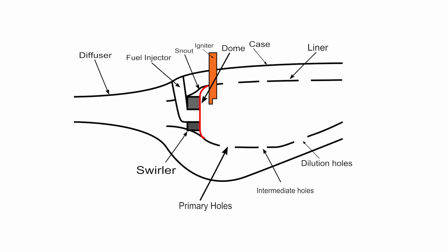The other type of liner cooling, transpiration cooling, is a more modern approach that uses a porous material for the liner. The porous liner allows a small amount of cooling air to pass through it, providing cooling benefits similar to film cooling. The two primary differences are in the resulting temperature profile of the liner and the amount of cooling air required. Transpiration cooling results in a much more even temperature profile, as the cooling air is uniformly introduced through pores. Film cooling air is generally introduced through slats or louvers, resulting in an uneven profile where it is cooler at the slat and warmer between the slats.